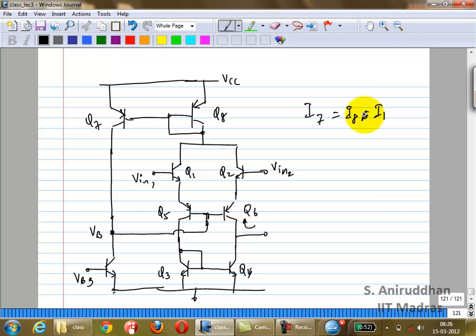This is what it's going to do. You have a current mirror here. Let's say this is I1. Sorry, I should be careful. Maybe I should call it IA. If this current is IA, it will make these currents approximately equal. There will be some errors because of betas of the PNP and so on. But overall, it will move towards making that happen.